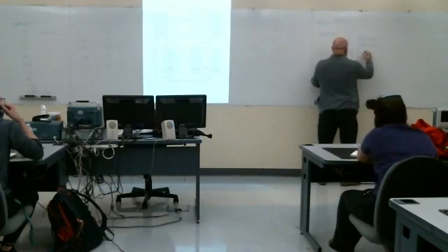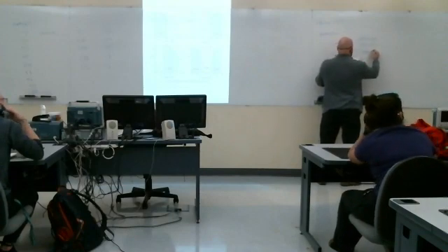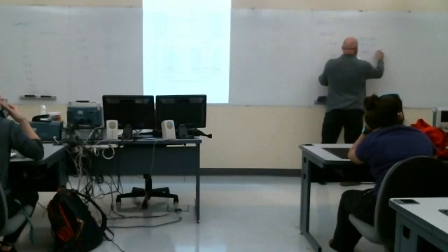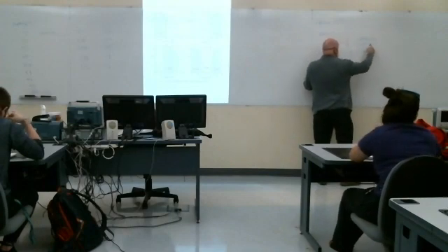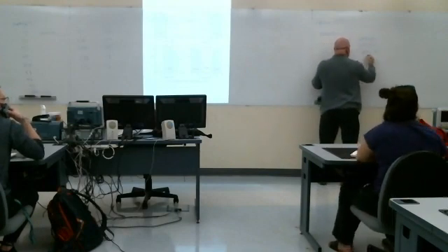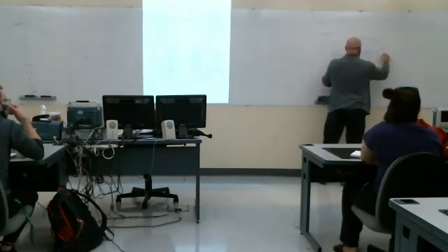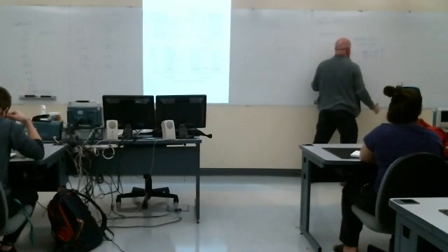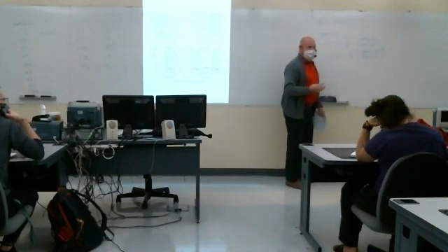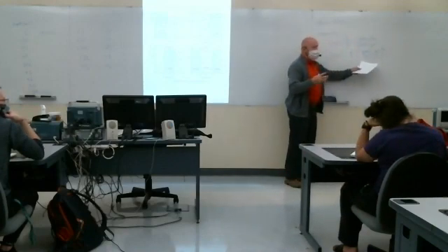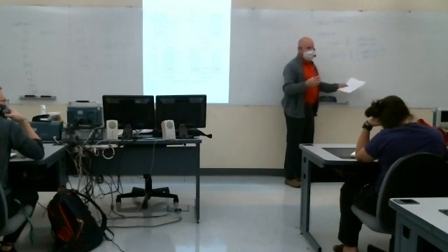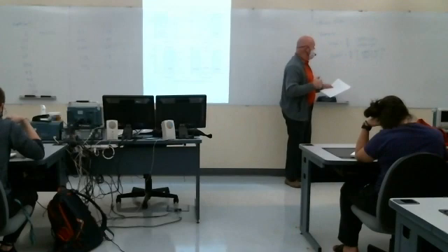We need the square root of the sum of the squares. Again, you don't square the j. That would be the magnitude response. It's just a real function of omega. There are no j's in this. So you could plot the magnitude response pretty easily on your calculator.